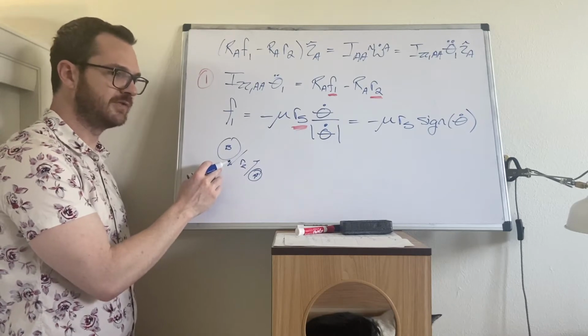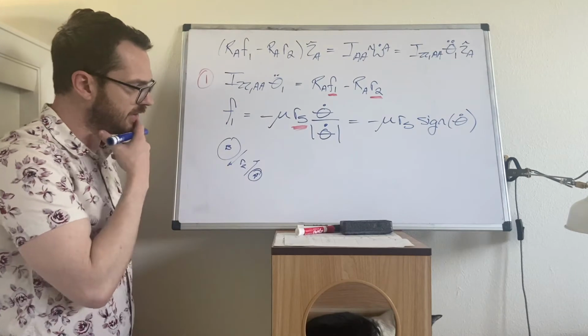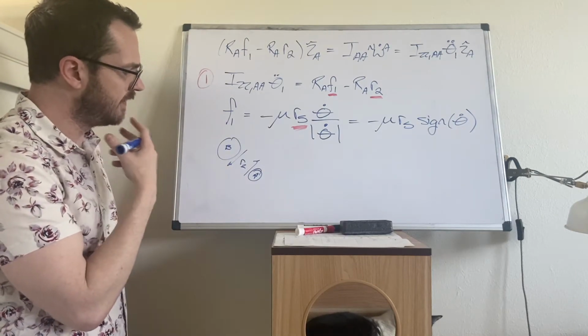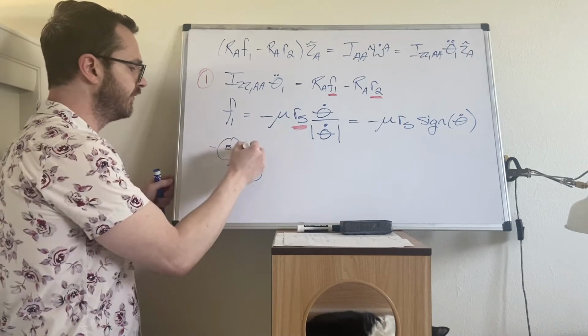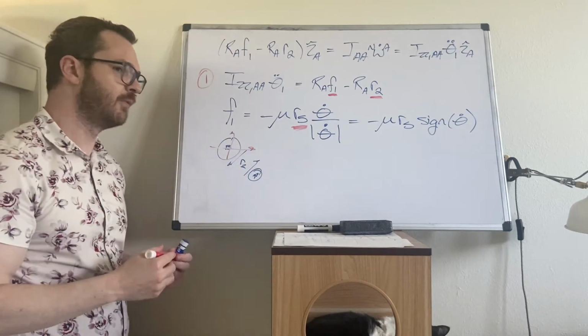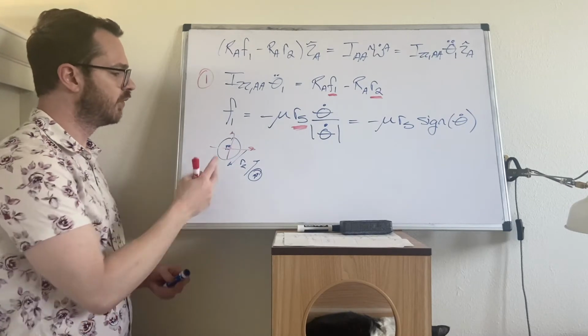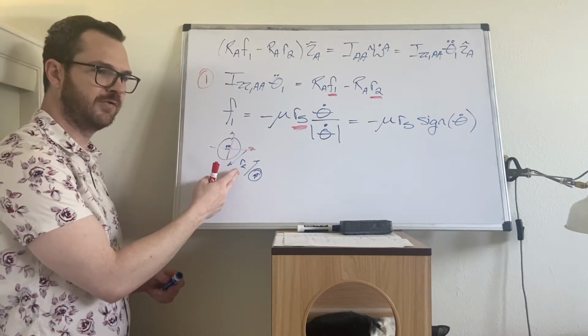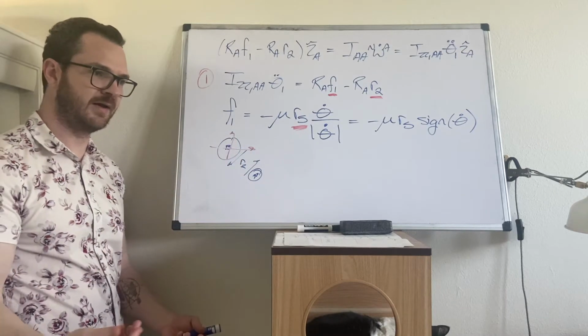Let's look at the equations for B. Now, you've got them in your notes, sum of forces and sum of moments. The sum of forces equation has the reaction forces at that pin joint, and we don't know those reaction forces. So if you do the sum of forces equation, you're just going to solve for R2 in terms of these two unknown reaction forces. So again, how does that help?